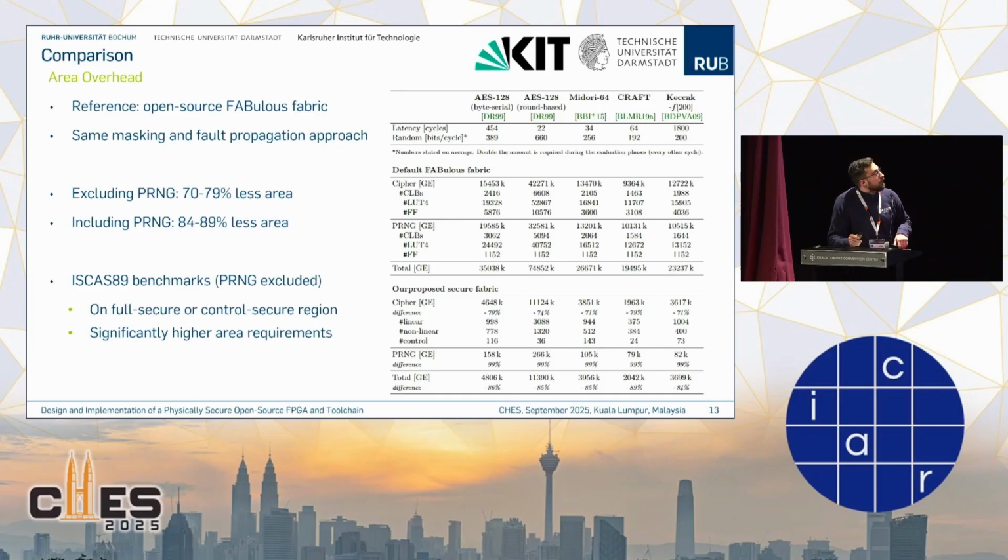Yeah, so we took this selection of ciphers and then we protected them using the same design flow. So basically we again synthesized them and used AGEMA to use LMDPL gadgets. And then for a reference design, which is comparable to a conventional FPGA that uses lookup tables, we need to map the LMDPL scheme into the lookup tables basically, which requires a lot of area, while in our approach we can just directly take the configurable gadget blocks.